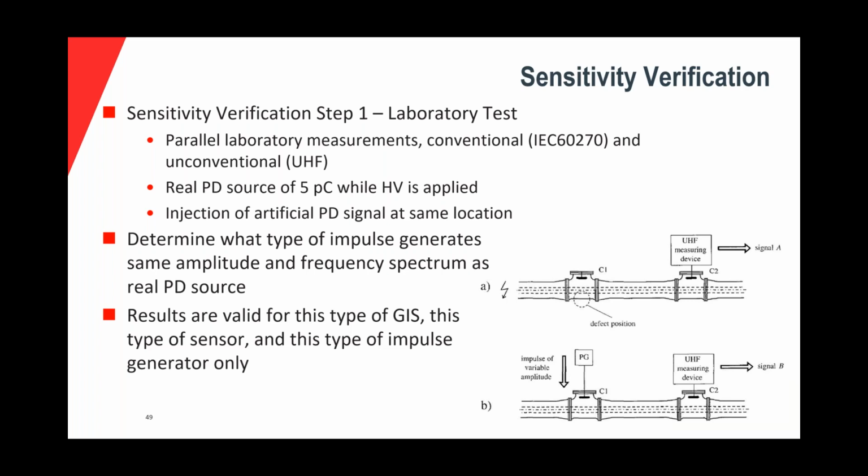Then the level of that 5 picocoulomb, how many dB microvolt it causes, will be registered with the UHF sensors.